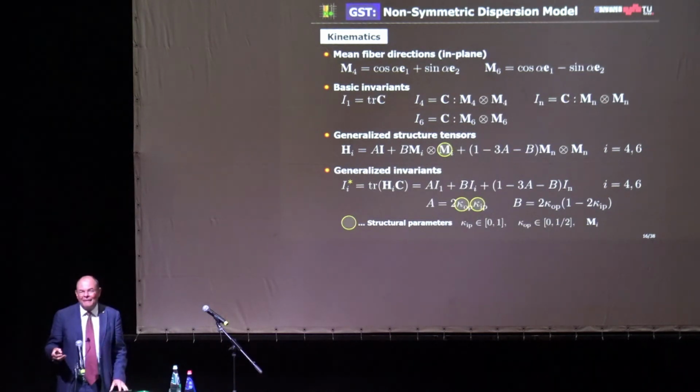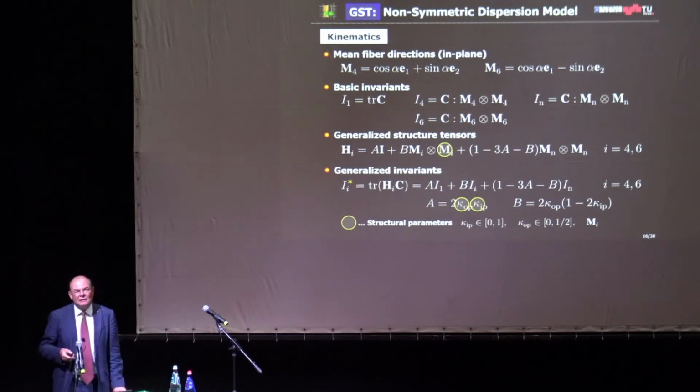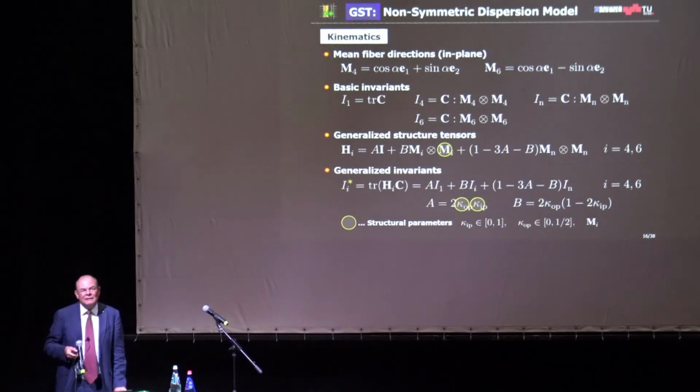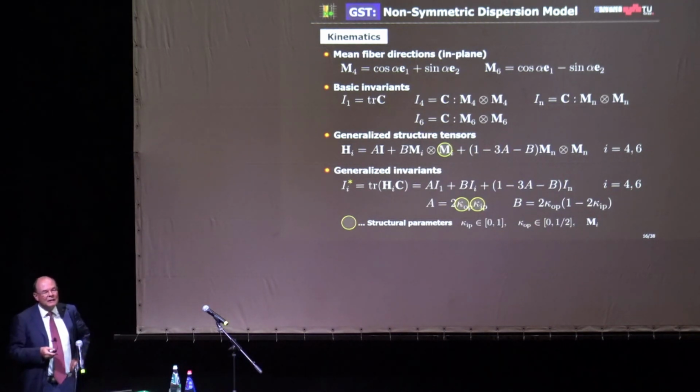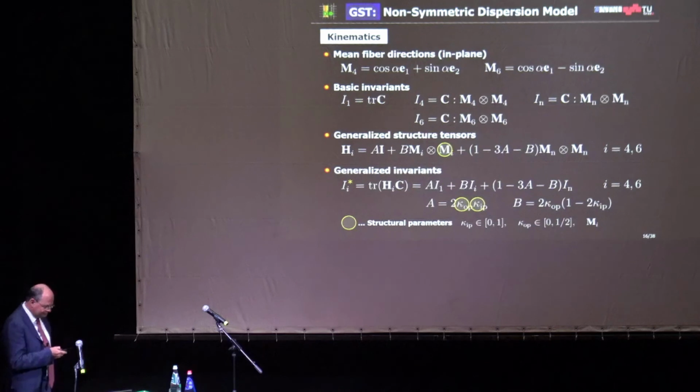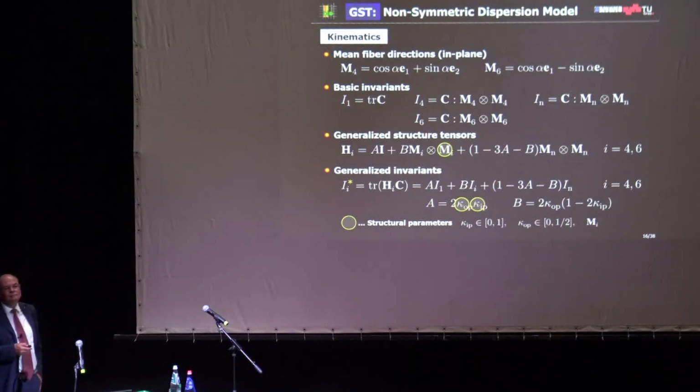My point is different. If you speak of symmetric tensors, stress and strain, you have 6 components. And you can take these 6 components as 3 principal directions being the same for stress and strain, but then it's isotropy. And then you have 3 invariants. You can take whatever you want, but these are scalars. And what you said, the second summand is anisotropic. This is I anisotropic, I think.